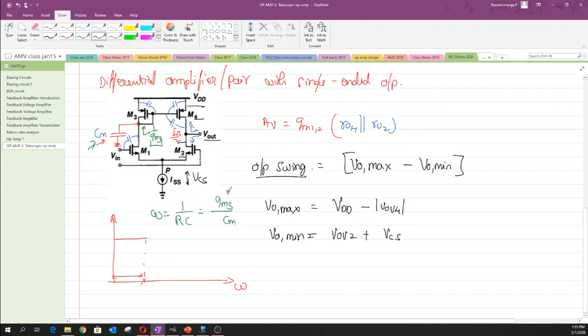And we know that the value of this gm3 is always small, but we also know that the capacitance value is large. So what is happening is that effectively the pole frequency of this is getting reduced, okay. So hope that you are clear with these circuit conditions, and due to which the pole is getting closer and closer to the DC conditions, and due to which the bandwidth of this particular circuit in general will be small whenever we have this kind of mirror structure, something like this, okay. Yeah. So hope that it is clear.